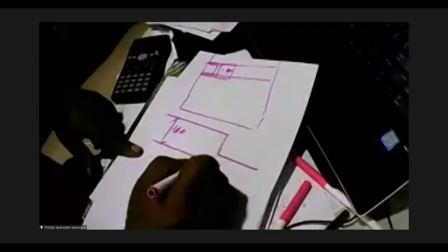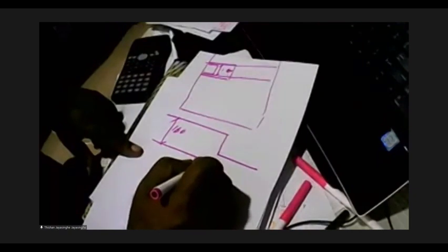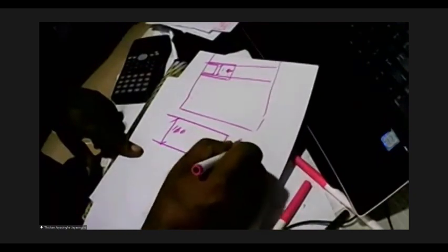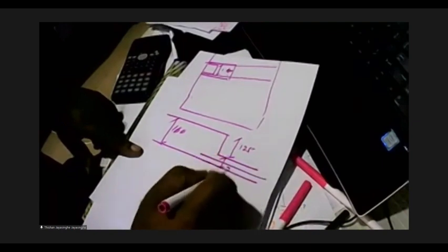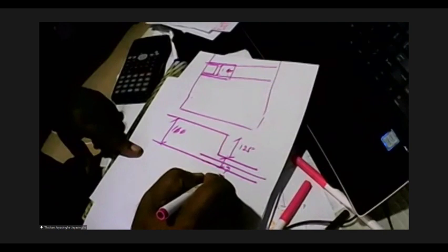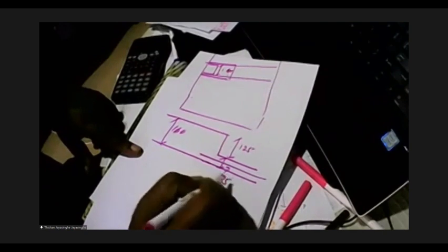So in these drop areas, we have a slab thickness of 160, and if you need about 125 drop, you might get only a thin slab of 35 millimeters.